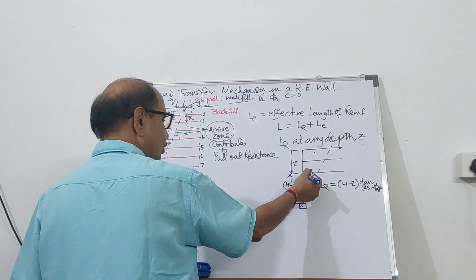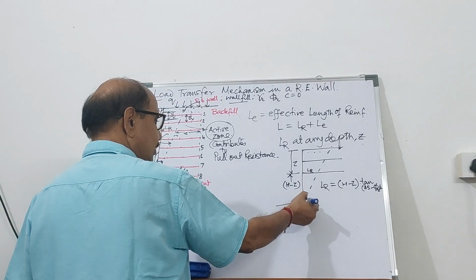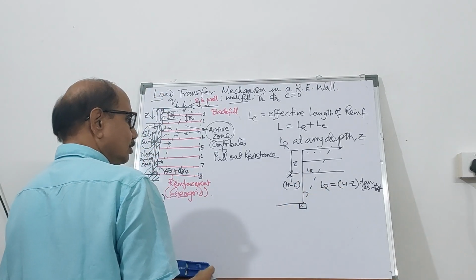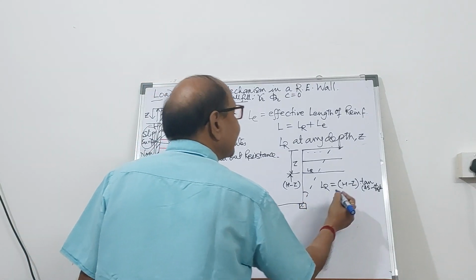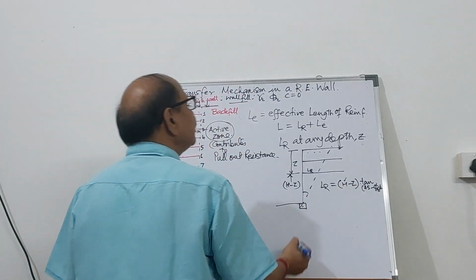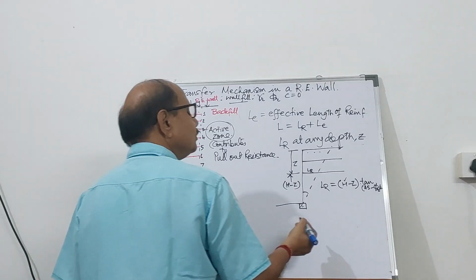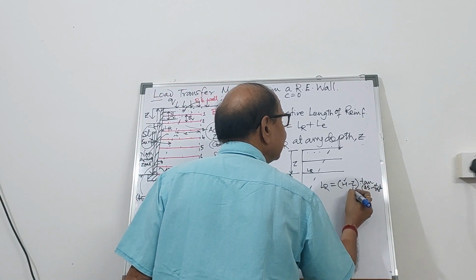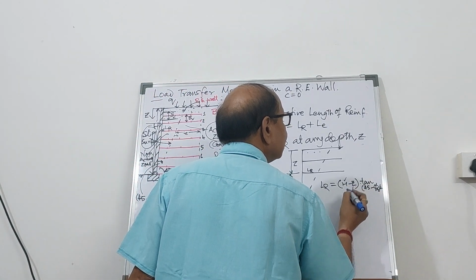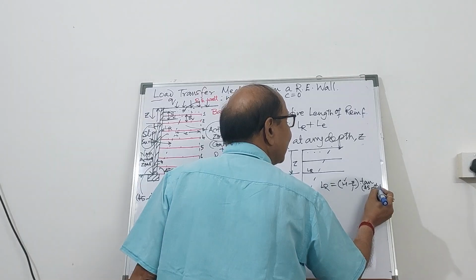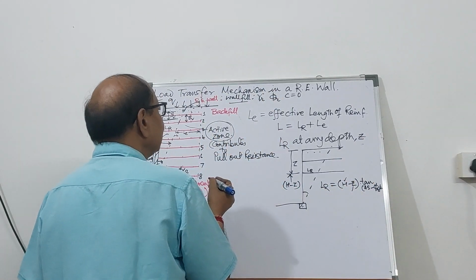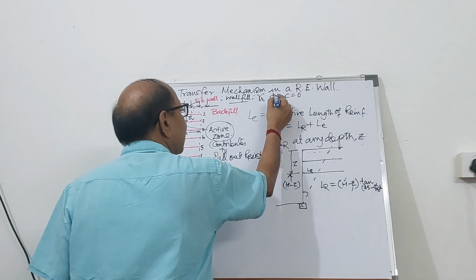This is going to be opposite side divided by this. So h minus z. H is known to you, the total height of the wall you are going to construct. Z at any depth you can find it out. Phi r is already known to you, the wall fill internal angle of friction.